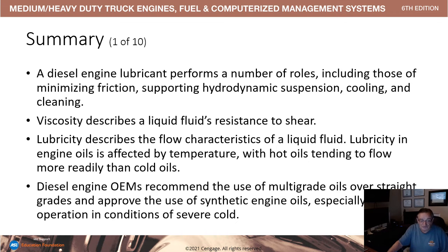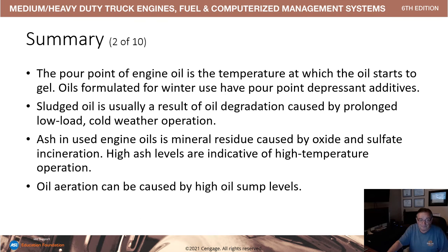Viscosity is the liquid's fluid resistance to shear. Diesel engine oils have recommended multi-grade oils over straight grades for many years now, and they improve the use of synthetic oils, especially for severe cold weather. The pour point of an engine oil is the temperature at which the oil starts to gel. Sludge is a result of oil degradation caused by prolonged low-load cold weather operation.